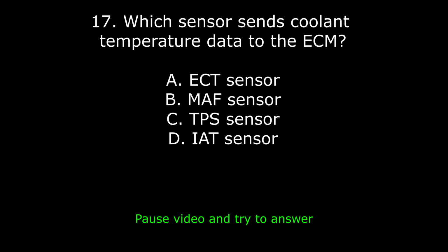41. When a voltage drop test shows more than 0.2 volts on a ground circuit, what does that indicate? A. Open circuit. B. High resistance ground. C. Normal reading. D. Battery sulfation. Answer: B. High resistance ground. Explanation: over 0.1 to 0.2 volts drop indicates poor connection, increasing resistance.